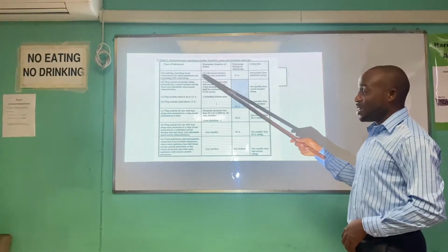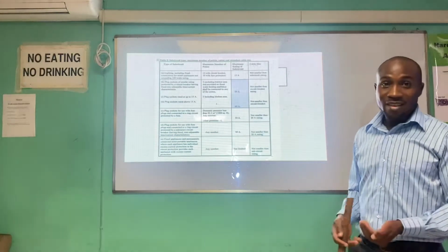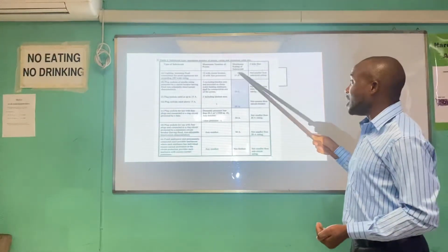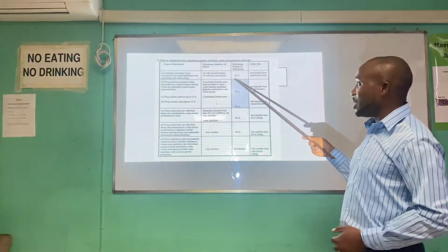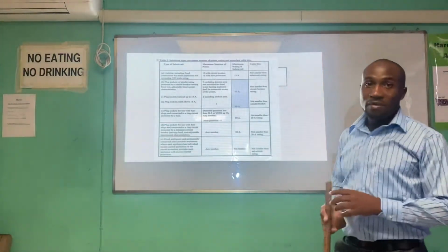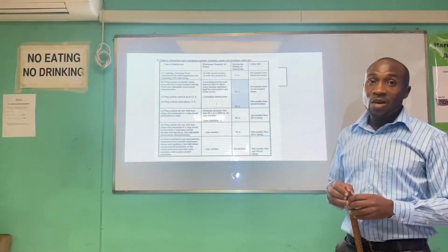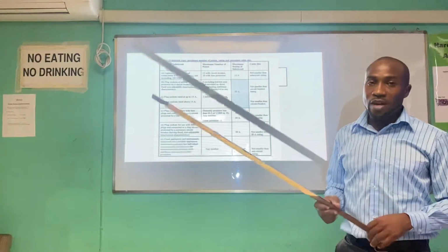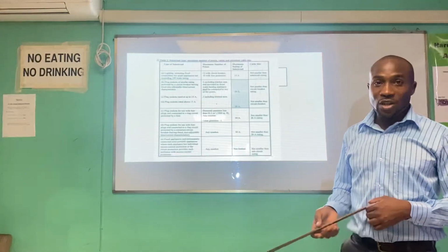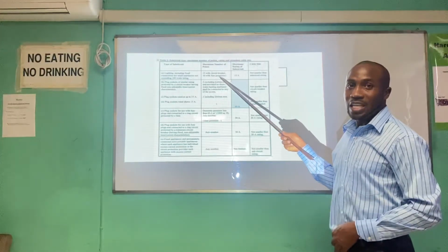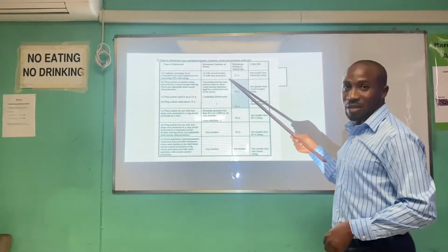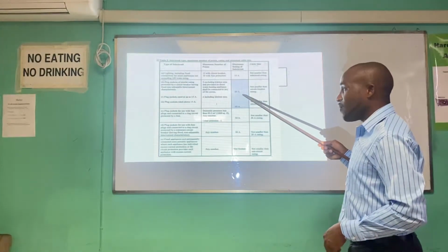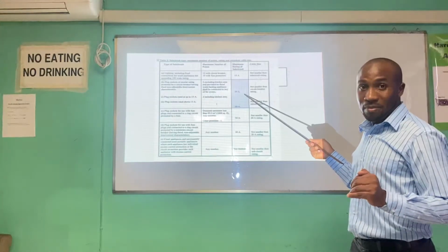Right, and the similar case for the lights. Say you have 50 lights at your house and you want to know the minimum amount of light circuits that you need, you would have 50 divided by 12. So the minimum there would be basically 5, because 12 by 4 is 48. So that's 4 circuits, and you still have 2 more lights that need to go on. So you need another circuit. So that would be 5 15 amp circuits. So you'd have 5 15 amp breakers here, and you'd have 4 20 amp breakers here minimum.